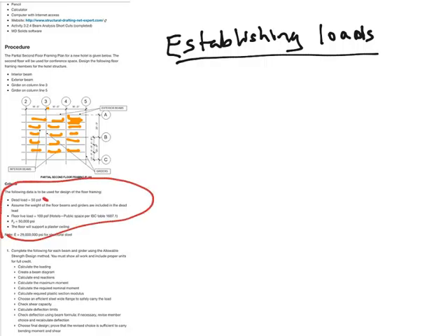I specifically want to call out the dead load and the live load. The dead load is 50 pounds per square foot, and the live load is 100 pounds per square foot. So if I look at this image here, I have an area on this beam. If this is my beam here, and I'm looking at that beam right there, and I go halfway between this beam there and the next one below it here, and look at that tributary width.